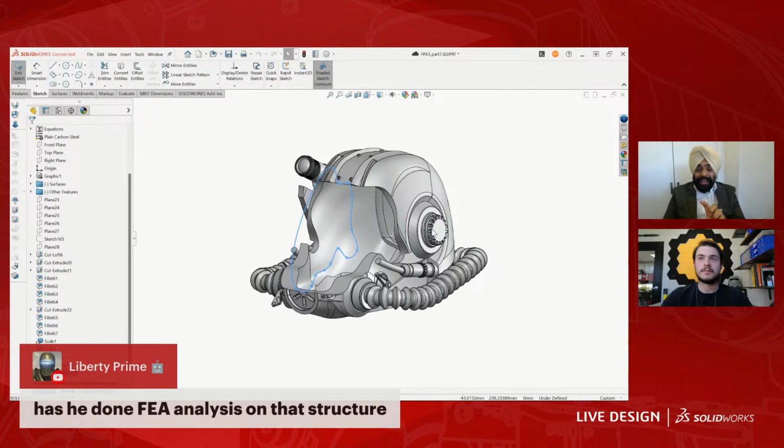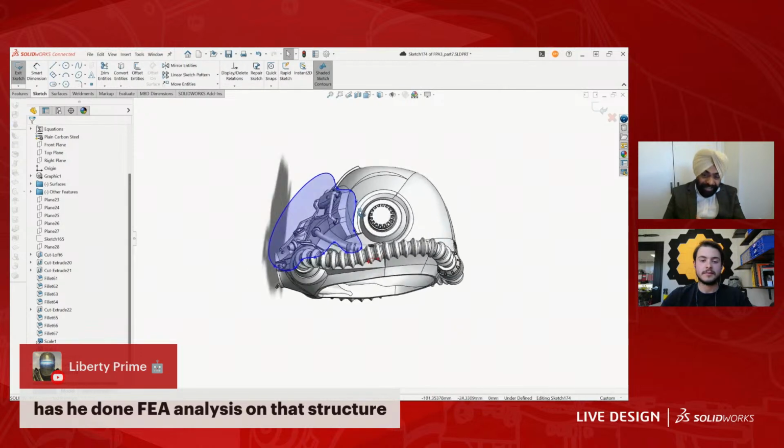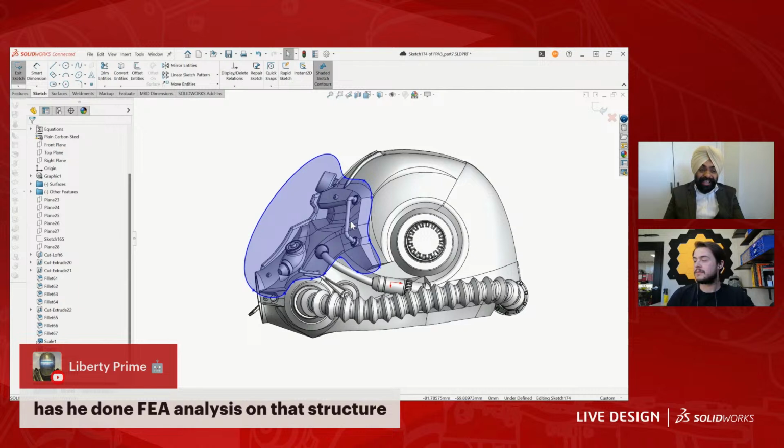It is going to be, I would say, a 3D split that eventually has happened, and then you removed one portion, copied the body, and then used the boolean operation to create another cutout, and then used configurations to manage it, so that once you create the assembly, you are going to add different configurations of the same part, and then you are going to add the rest of the features. I think it's truly amazing.